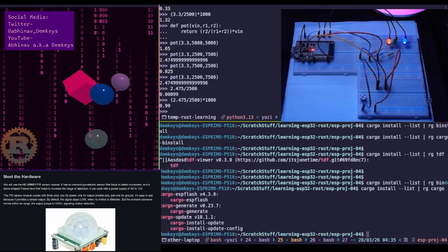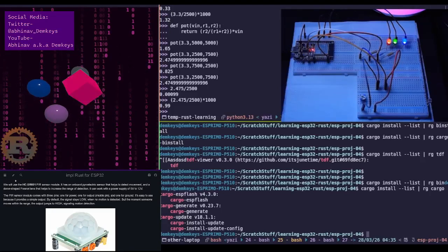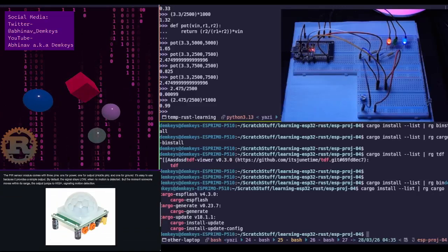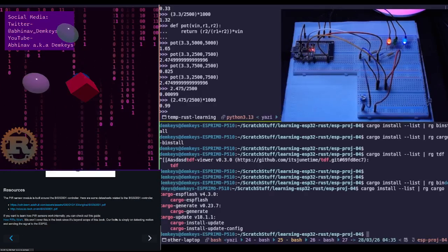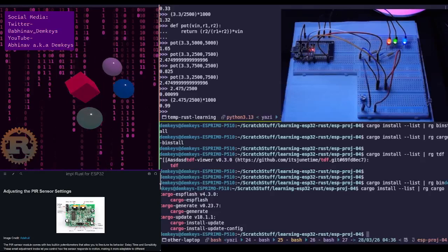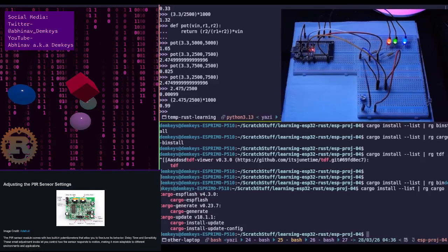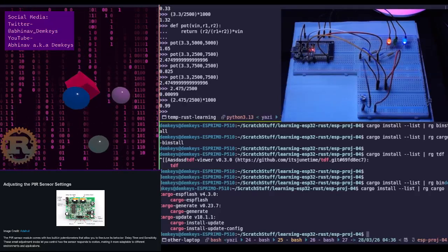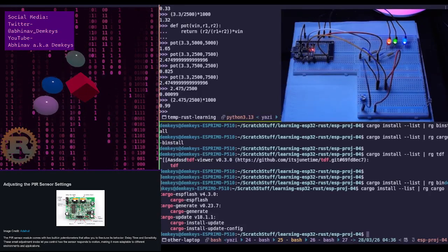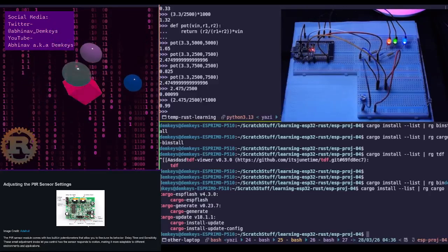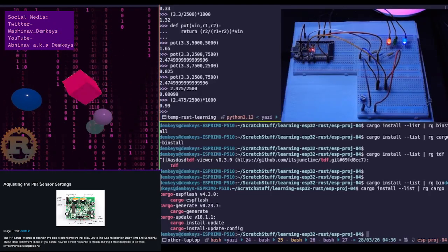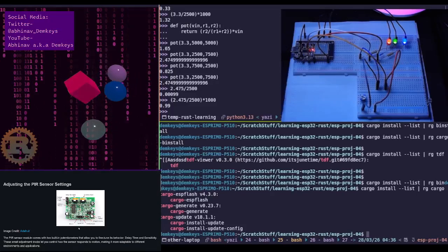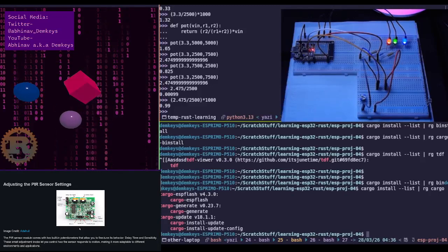So I do have this sensor as well, this module, in fact. And how are we connecting all of these? Oh, there's only three. Okay, so there's ground, there's digital out, and it says here 3 to 5 volt VDC power. So I'm guessing the way this works is it's basically always putting out information. You're not really controlling too much else.